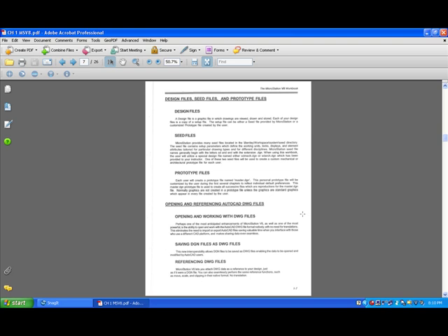In other words, it's the same as the design file, but some people have seed files set up that have all preset information, might be dimensions, working units, screen size, tools. All of those things can be preset into a seed file, so when you bring it up you don't have to reset it. Another drawing might come up in meters, and you have to change it to feet and inches. In this case you can have a seed file that's already set to feet and inches. When you bring it up, everything is set the way you like it.